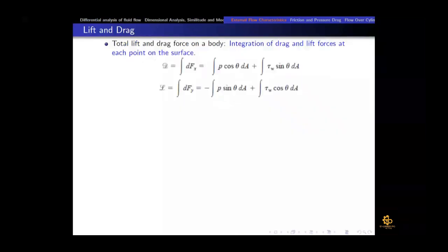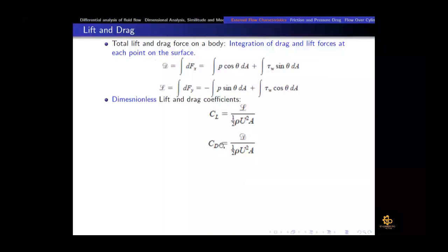So we learned from chapter number 7 that if we want to compare different things or characteristics of any fluid, then we want to show them in some non-dimensional parameters, which we also call pi terms. So for this drag force and lift force, we define two non-dimensional parameters. One is called coefficient of drag, which is CD, and it is very common in fluid mechanics applications. You can even calculate these CD and CL values using your CFD simulation, which you must be conducting these days, by the post processing in ANSYS software.